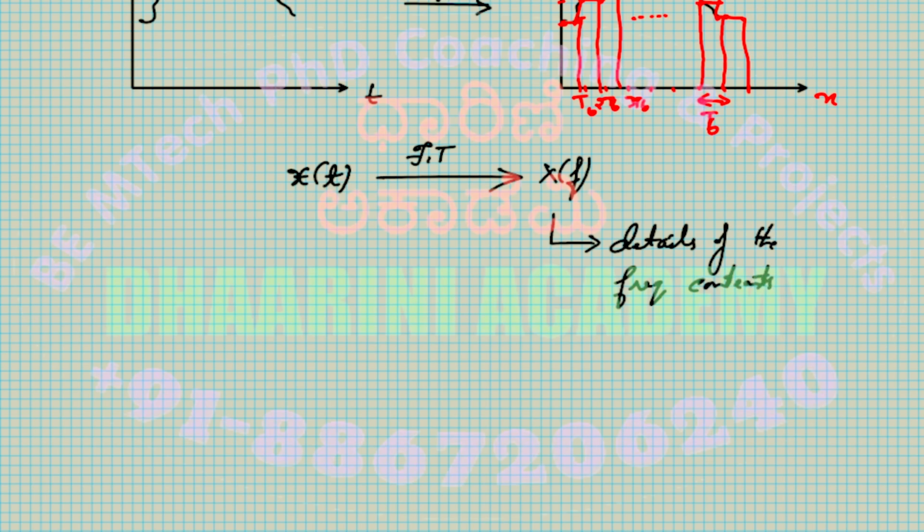You come to know whether the signal has 20 hertz, 50 hertz, 80 hertz, 120 hertz present in it or not. If the amplitude is high at a frequency, you can say that frequency is present. If it is not, you say that frequency is absent, not present. So this is the first idea.